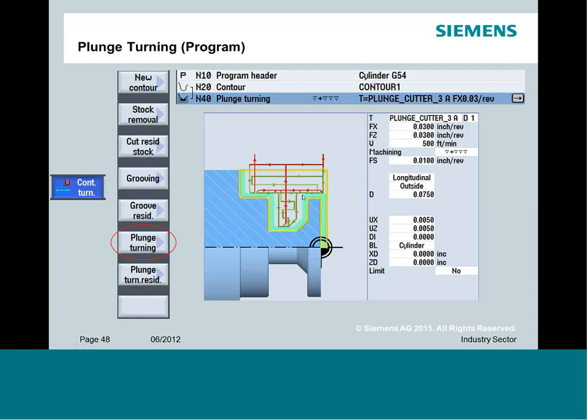Certainly you have to be aware of the tooling you're going to use. Not all grooving tools, actually most grooving tools, do not like to side turn. So there are specific tools that the cutter manufacturers have created that allow you to do this type of operation, and they usually refer to them as groove turn tools. A lot of them are a dog bone style insert.